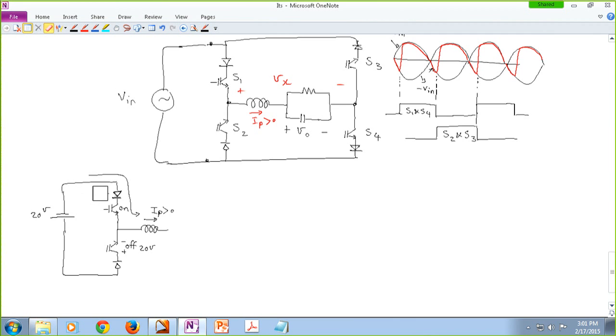All right, very good question. Does the diode have the capability to handle the current? Oh, the question is, can this diode handle the current? That depends on your design. What is the value of this current? What is the average value of this current? Then you have to pick a diode that can handle that amount of current. It depends on your power rating, basically. Is that the question?